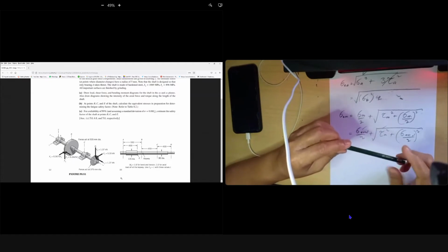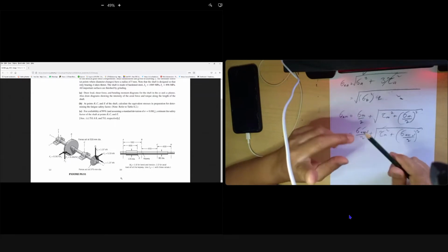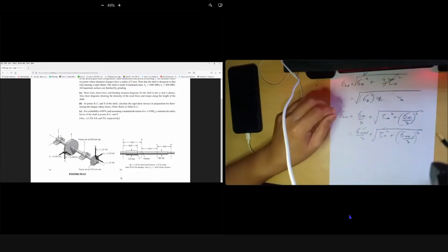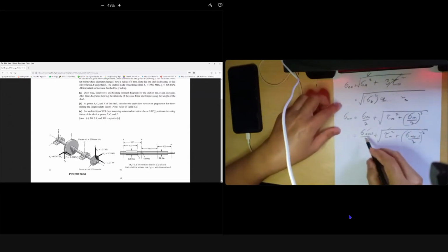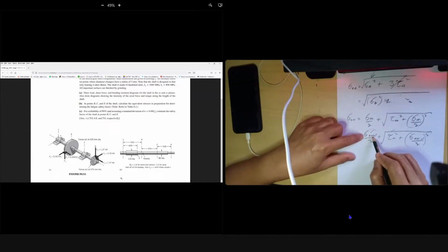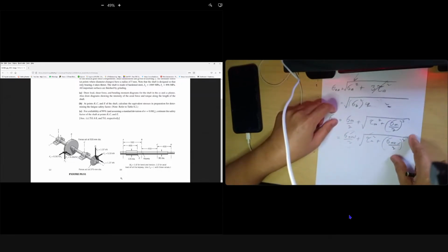I can't recall, but normally we rarely have that kind of case. Be careful, because if it is like this, there is no M, so I get a negative axial load, so I understand. So it becomes 0. This is compression, so it becomes negative, right? If we have axial load in compression mode and this value is negative, we square it.